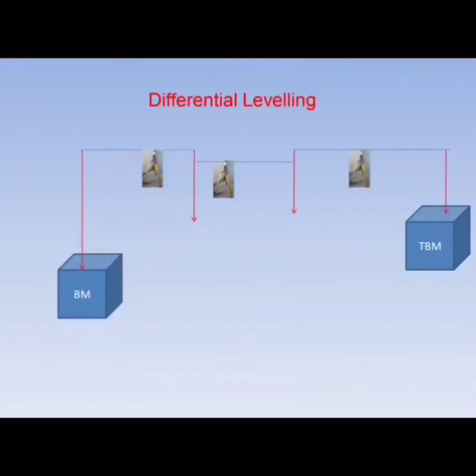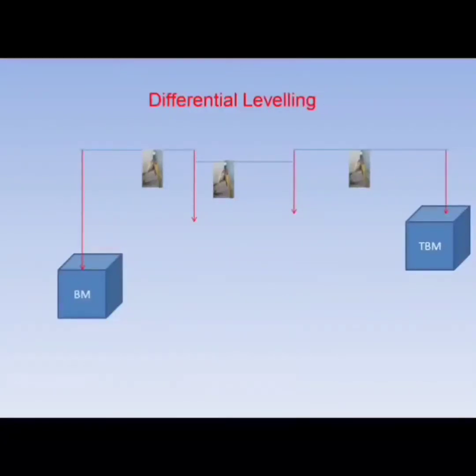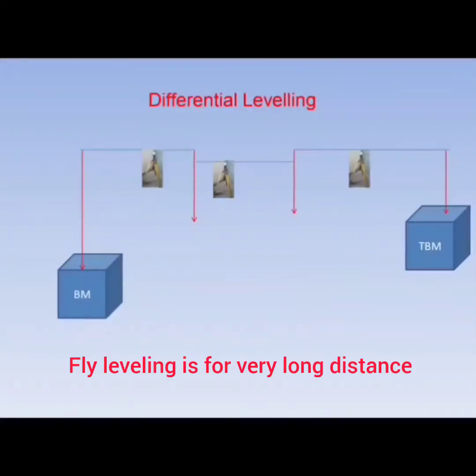We have to shift the instrument a number of times to carry out the leveling. Profile leveling is done for laying of roads, railway lines, pipelines, etc., when the distance between survey points is very long.